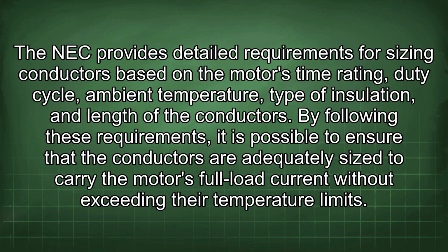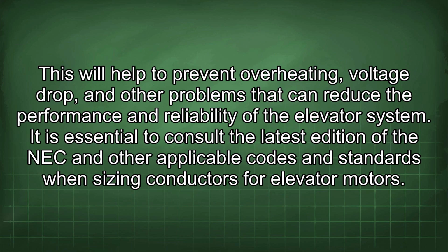By following these requirements, it is possible to ensure that the conductors are adequately sized to carry the motor's full load current without exceeding their temperature limits. This will help to prevent overheating, voltage drop, and other problems that can reduce the performance and reliability of the elevator system. It is essential to consult the latest edition of the NEC and other applicable codes and standards when sizing conductors for elevator motors.